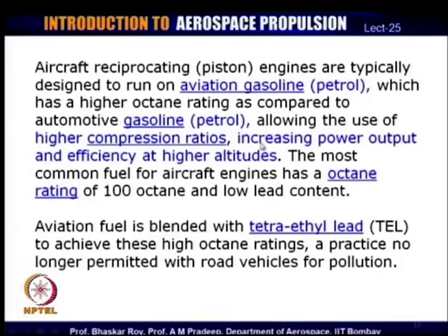Now, this kind of fuel is typified by what is known as high octane value. An octane rating is given in terms of 100, and aircraft fuels are often of 100 octane, and they often have a small amount of lead content. This lead is tetraethyl lead, which is blended with the basic fuel, some variety of petrol, and provides a high octane rating.